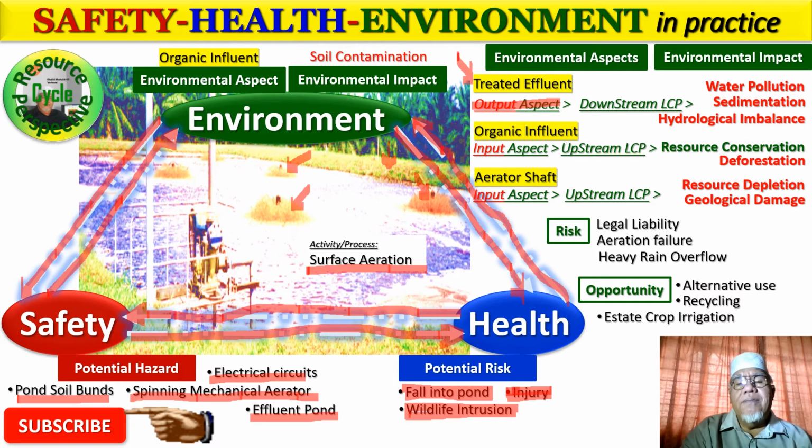Concentration multiplied by flow rate, you get a high organic load, not due to the concentration of BOD in the region of 100 to 150 milligram per liter, but when you have 20 to 70 to 100 meter cube per hour, can you imagine the load? That will eventually, despite the fact that they are able to meet the regulation or the permits of their discharges, still cause water pollution because of the load.